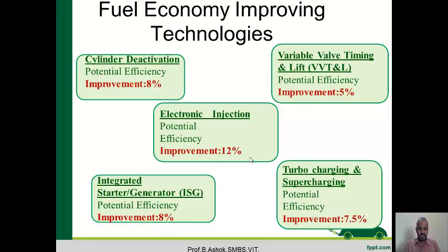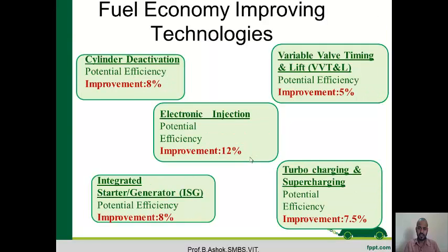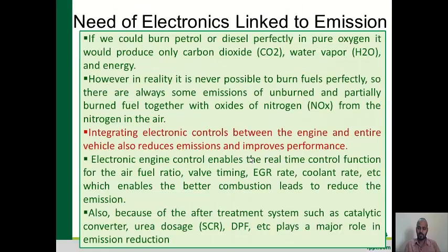And the integrated starter alternator is nothing but integrating the starter and alternator both in a single component, because the starter works only at the beginning, and the alternator works the rest of the time the engine is operated. So there you can improve by 8%, and with turbocharging and supercharging you can improve by 7.5%. So these are the technologies related to fuel economy improvements. And next, the link to the emissions.